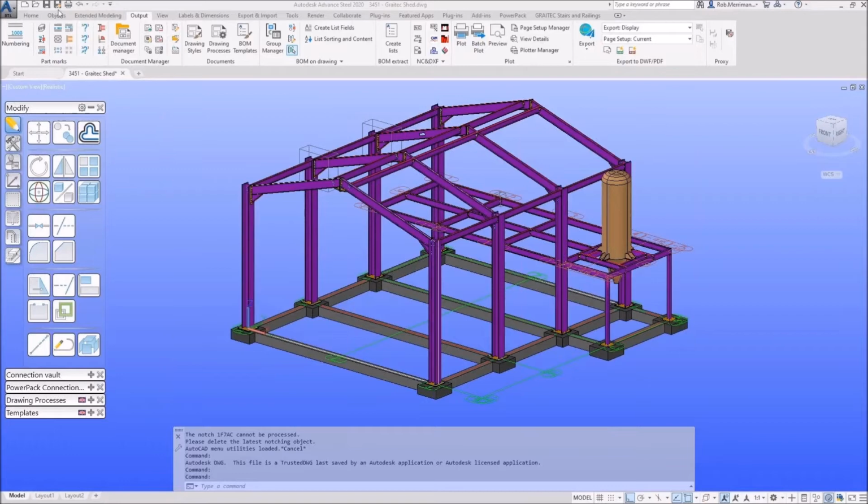Now, the important thing before using any of the tools in this marks panel is that everything is controlled by the toggle here. This switches you between the assembly numbers, the single part numbers and the preliminary numbers. So any of these functions that you use here are driven by the toggle. At the moment we can see in the toggle that nothing is orange on the little icon. That means we're on the assembly numbers.